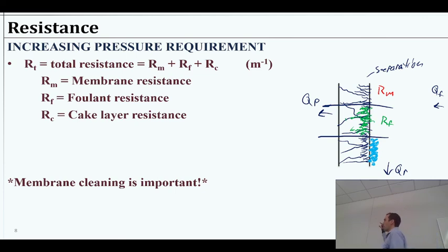The fact that we have this retentate stream should gather most of the rejected stuff in the first place. So what we're building up is not days and days of grime that had nowhere else to go. This is actually just trying to knock whatever we can off of the membrane. So in fact, sometimes it'll be every minute or every 10 minutes, 20 seconds of backwash. So it's just a quick clean, shake it off, try to do something to physically dislodge it.